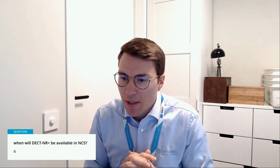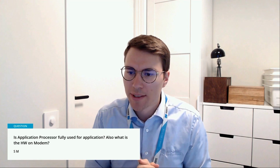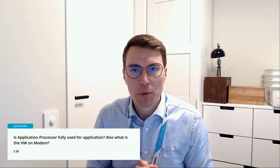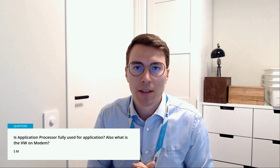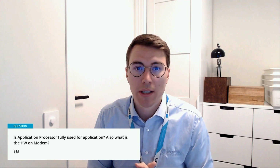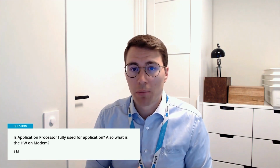Next question. Is the application processor fully used for the application? Also, what is the hardware on the modem? So yes, the application processor is open for the user to program their application, and it's dedicated only for their application. Basically, you have your own flash and RAM there. The modem is separate inside the SiP, with its own dedicated flash and RAM.